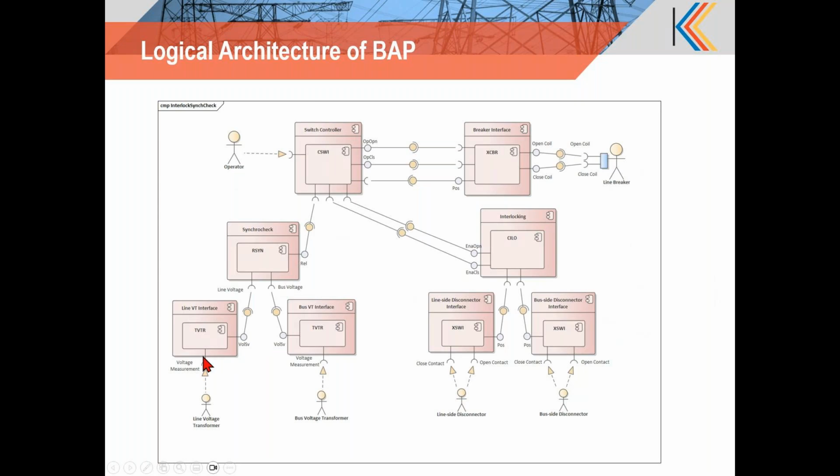And we also had the merging unit collecting the voltage and currents from the system. So this kind of general topology helped to prepare all these devices. Most of the bays will have merging units collecting the information from the system, passing it to the protection devices, and the bay controller allowing the control to the system, providing synchro check and interlocking functions for the HMI user to control the circuit breaker.